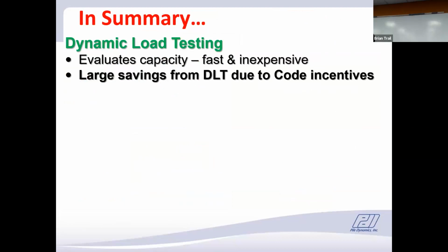So we'll try to summarize what we've done today. For the dynamic testing that Frank talked about, and I sort of finished up on, it evaluates the capacity. It's relatively fast and inexpensive. For sand soil sites, the capacity at the time of testing, of driving the pile, is probably adequate.